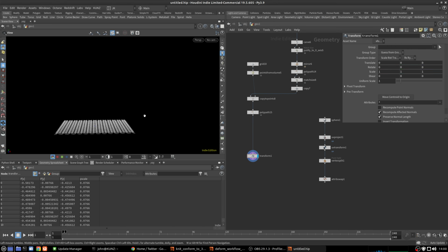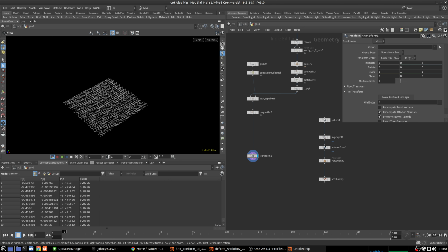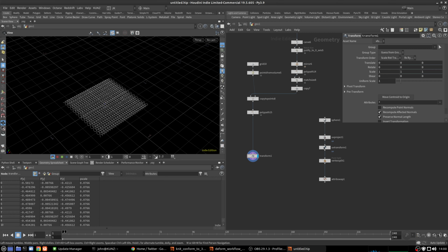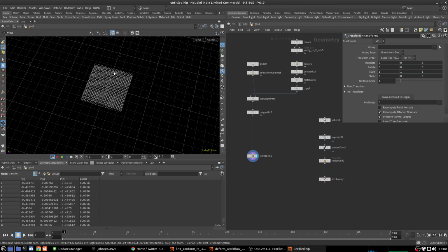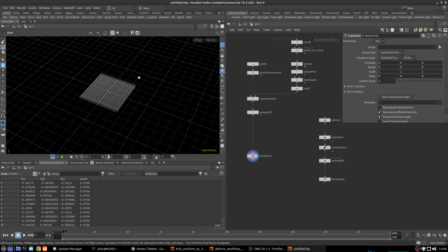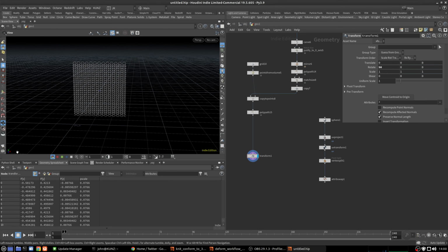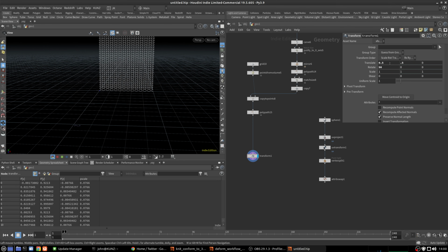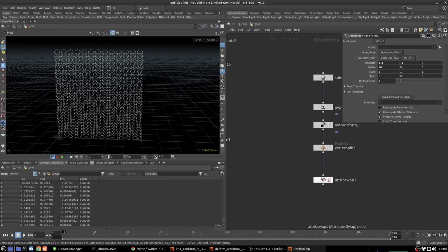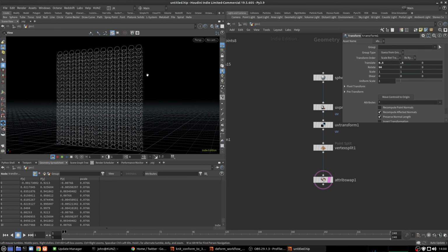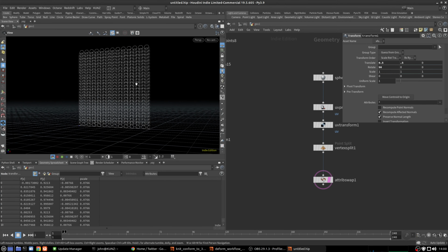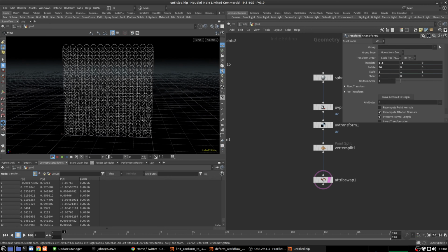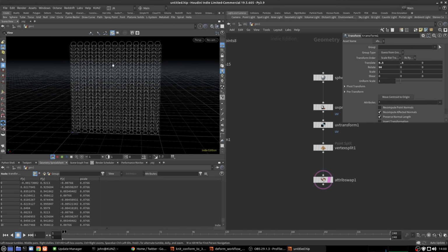And what I want to do is move this geometry that we're usually working with at the origin in a unit space on the XZ plane. And I want to rotate this 90 degrees. So now that we're kind of in the XY plane, I also want to shift it 0.5 and 0.5 like that. And now we should be closer to something that I'm calling UV space. So you can see here that this is kind of overlapping or matching the basic position of this sphere once we've swapped it into UV space.